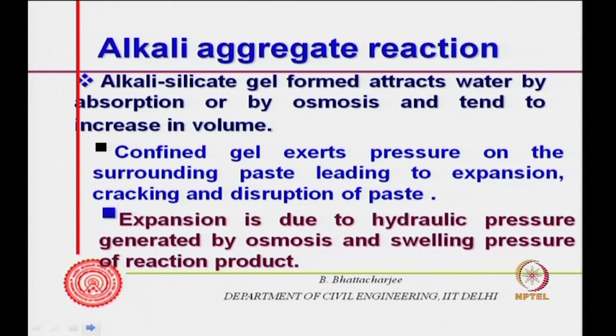So, expansion is due to hydraulic pressure generated by osmosis and swelling pressure of the reaction product, both. The reaction swelling pressure will come because the gel, with water, will try to expand, but at the same time there will be hydraulic pressure.